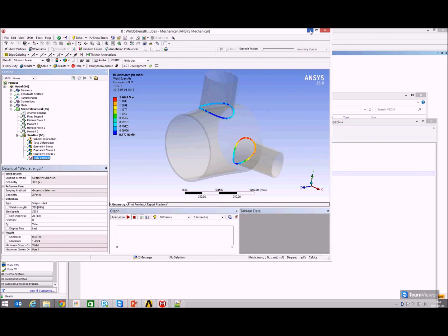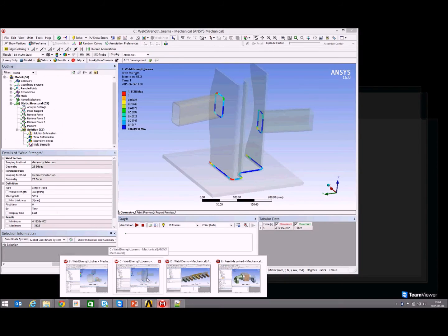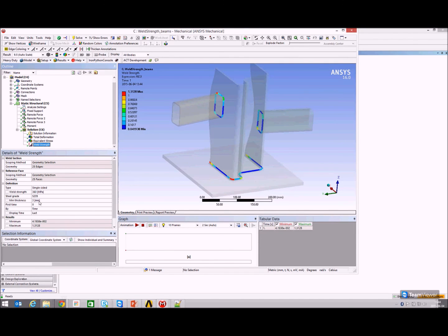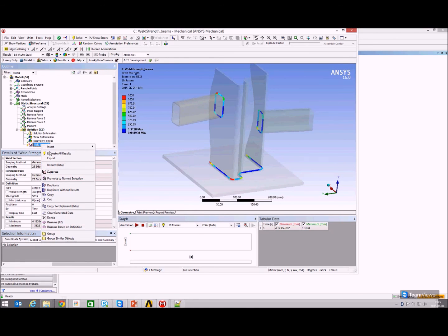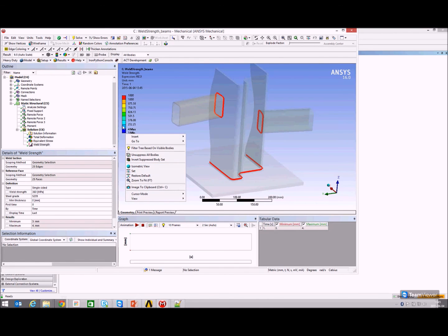So this is the Weld Strength utility. One final feature it has, which I can show on one other model here, is that you can use it for finding out the minimum weld thickness to use. Typing in 0 as thickness, evaluate, it will now iterate and propose the sizing. In this case, 3 mm is okay most of the time, and for these corners it proposes 4 mm.